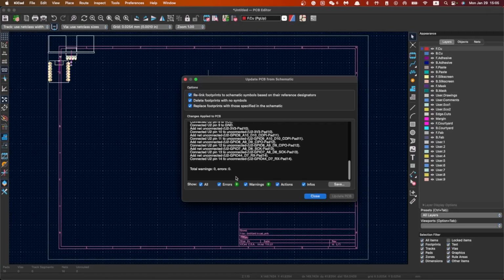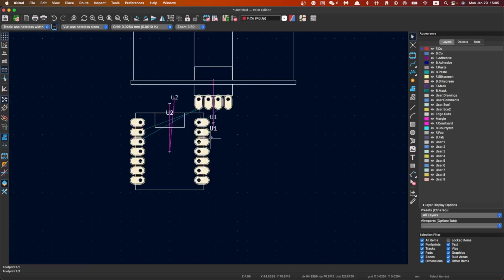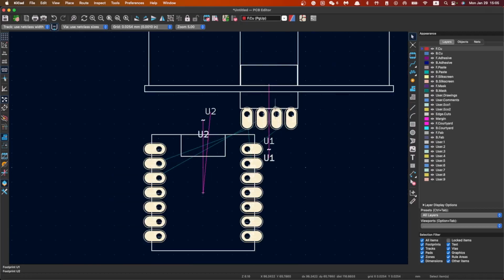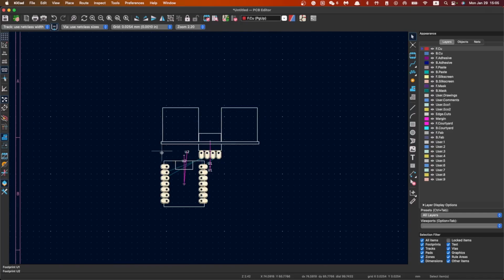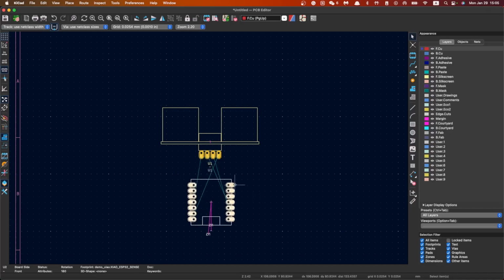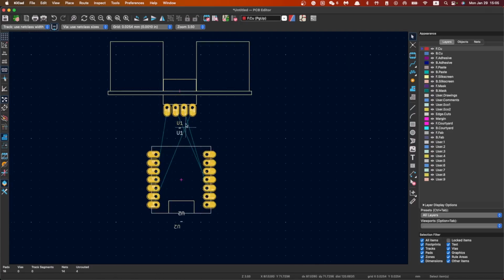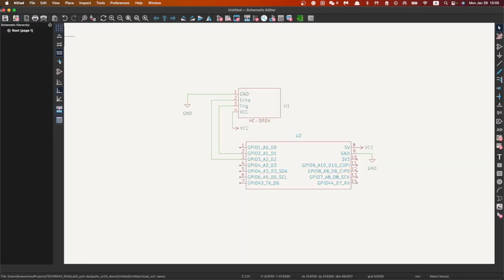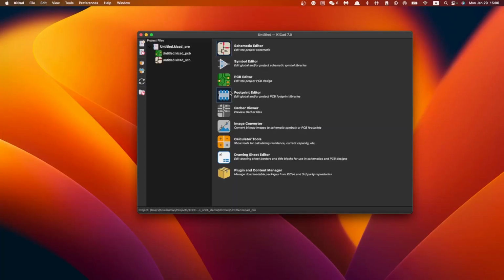Let's go to the PCB view and import them. Update. No error. Perfect. And you can see it is showing up that these pads shall be connected together to your device here. And I can definitely rotate it. What you need to do next is just route the tracks here to make sure those corresponding pads are being connected. Okay, so this looks pretty simple, I would say. So I'm just going to stop it here for footprint and symbol creation for your customized devices.